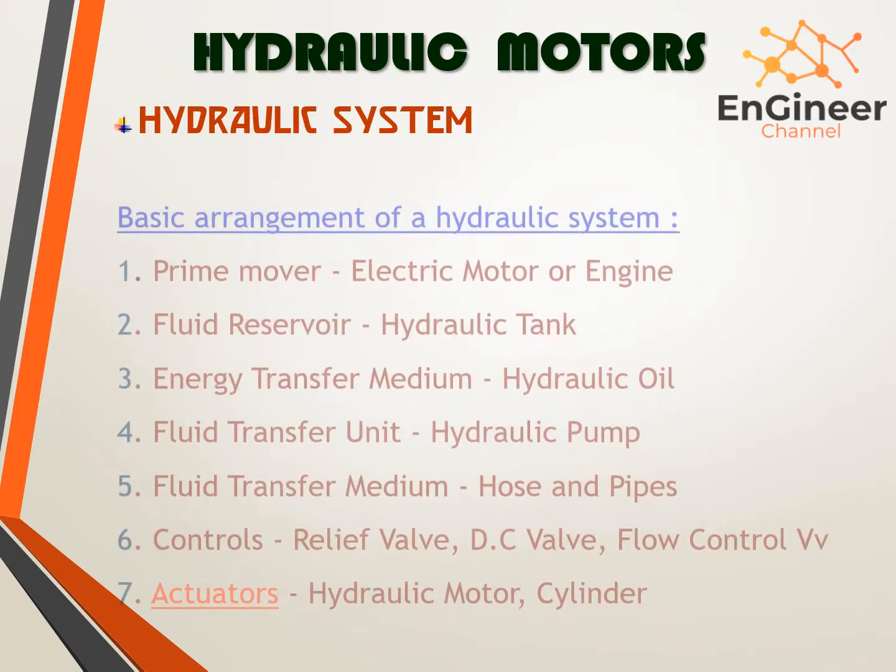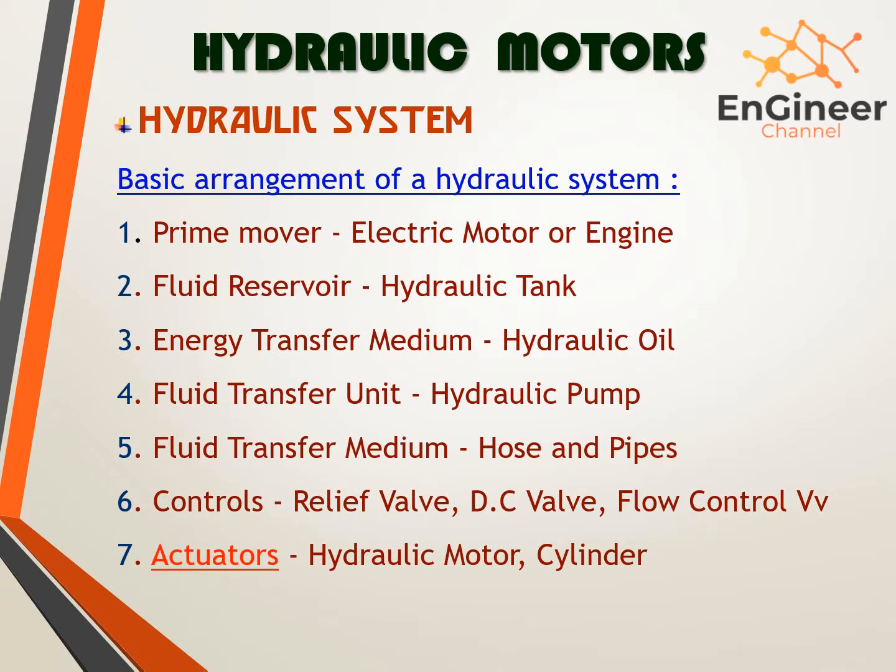Let's now discover the hydraulic system. The basic arrangement of hydraulic systems are prime mover like electric motors or engine, the fluid reservoir like hydraulic tank, the energy transfer medium like hydraulic oil, the fluid transfer unit like hydraulic pump, the fluid transfer medium like hose and pipes, the controls like relief valves, DC valves, flow control valves, and the actuator, which are the hydraulic motor and cylinder.